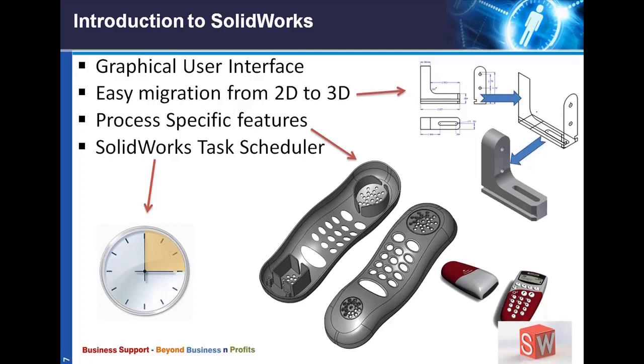So what you will do here, we open a separate Task Scheduler application which comes with SolidWorks, and you will show the path where the files have to be converted. So these will be converted into the new version which you want. You don't require manual input. You can give a schedule time, starting at 9 o'clock and ending at 5 p.m., and you can also do processes like printing the documents and creating drawings automatically by using templates, etc. You can do all this using SolidWorks Task Scheduler.